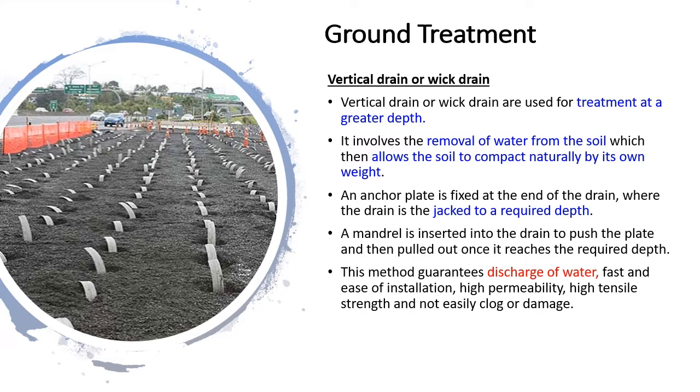Alternatively, horizontal or near horizontal bored drains can be installed from the toe of the face of the slope. Drains of this type are usually lined with a perforated or permeable material such as no-fines concrete rather than filling with granular medium. For maximum effectiveness, deep drains should extend well beyond the point at which the reduction in pore water pressure is required, probably as much as 2 or 3 times the drain spacing.